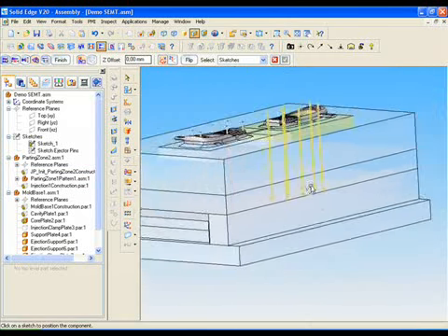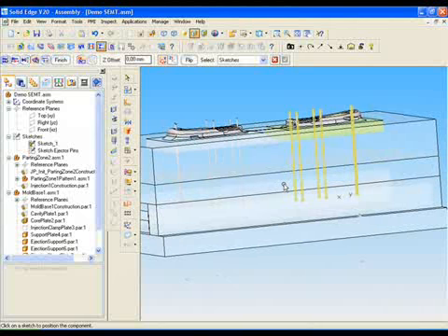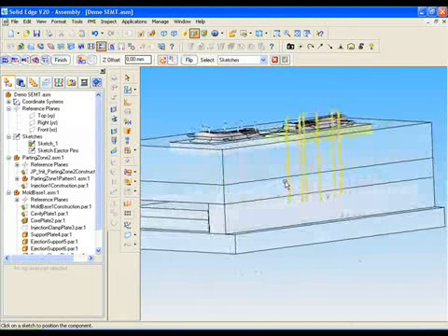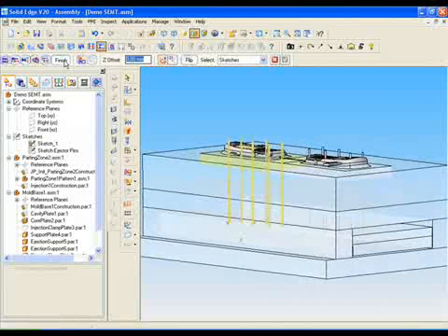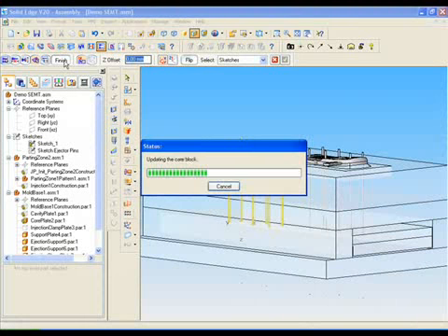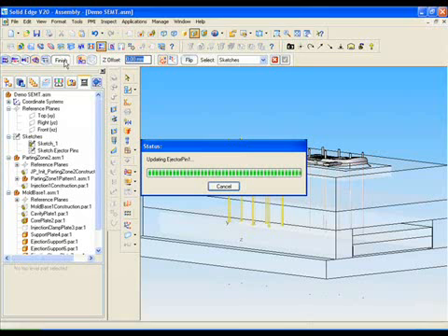The pattern is represented also in the instance parting zone, as it's a copy of the reference. We may now finish the command. The trimming operations of the ejector pins against the parting surface are made, and the intersections between the plates and the ejector pins are calculated so that the resulting holes are created in the plates.